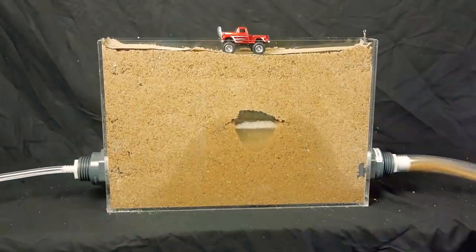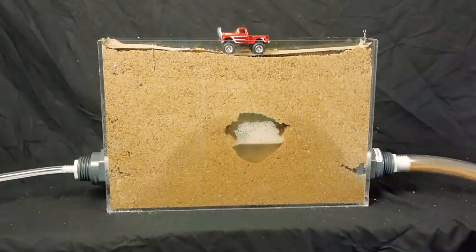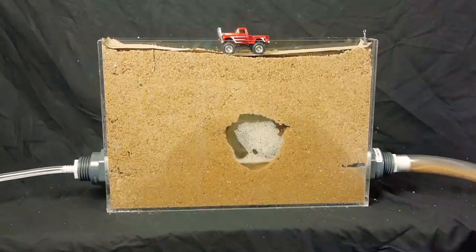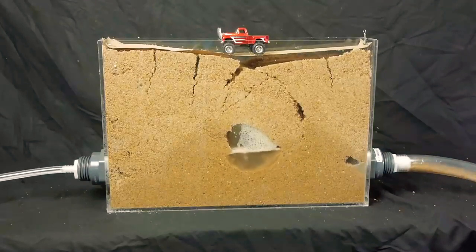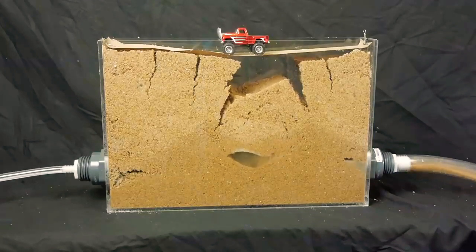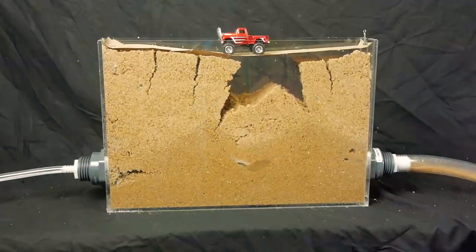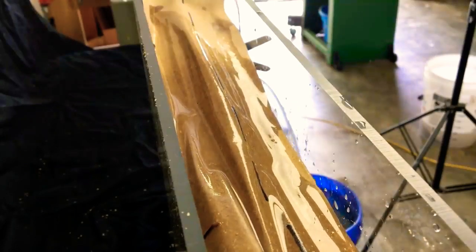As more soil is washed away, the subsurface void grows. Depending on all those soil properties we talked about earlier, this process can take days to years before anyone notices. Many of our subsurface utilities are placed directly below roadways, and the paving often acts as a final bridge above the sinkhole, hiding the void below. It's only a matter of time before everything above is swallowed up.